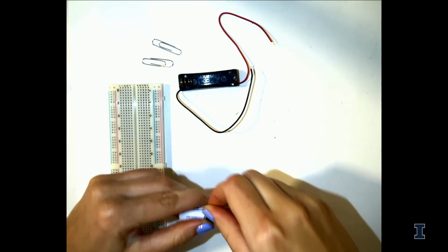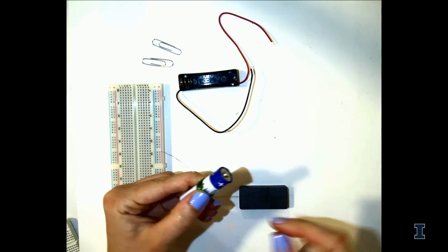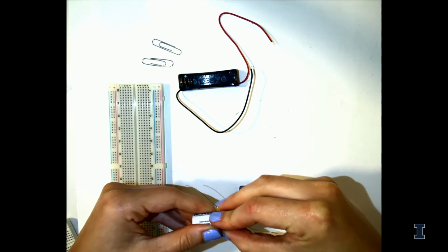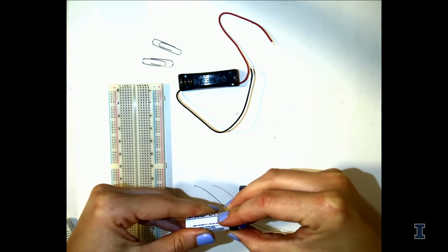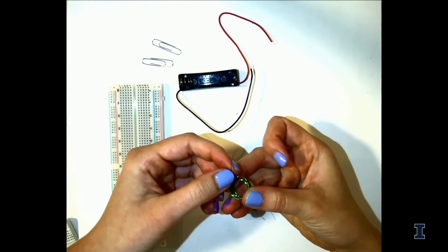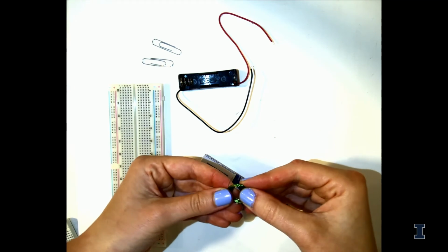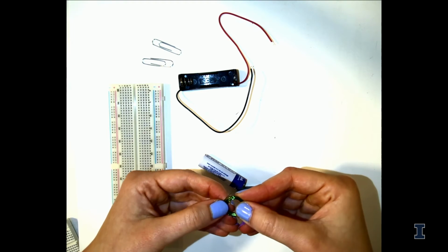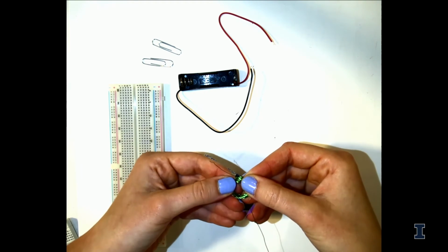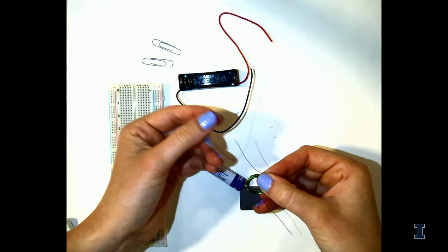So our battery is wound with wire. We have about 2 inches hanging off either end. So next up, you're going to pull the wiring off the battery. Make sure that it keeps its shape. Here we go. So you have a nice loop of wire. Make sure when you're winding that you always wound in the same direction, because what we're doing here is we want uniform current. So next up, you're going to take the 2-inch ends of the wire.